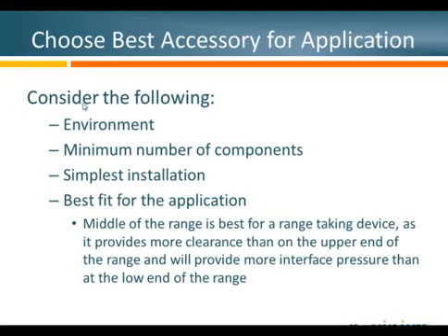If you're going to contaminate an environment, it's recommended that you go to a higher voltage termination in order not to have flashover, not to have reliability issues with it. And a lot of that is covered in the standard for terminations, IEEE 48.